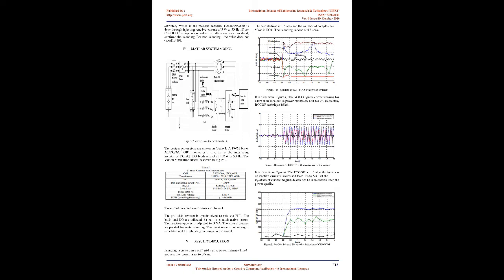It is suggested a method of intentional islanding. He has very elaborately pointed out different modes of inverters. Under grid connected mode, the inverters should be in CCM mode to share the loads proportionally.